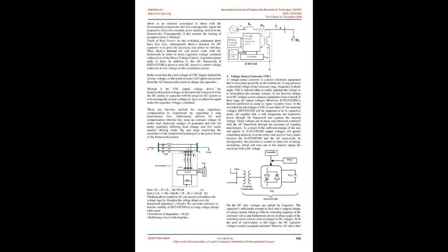At operation time, the line at the primary terminal is monitored continuously by D-STATCOM and is further compared with the reference signal. D-STATCOM consists of a two-level VSC, a PI controller, a DC energy storage device, an IGBT circuit, and finally a coupling transformer linked in parallel to the distribution network.